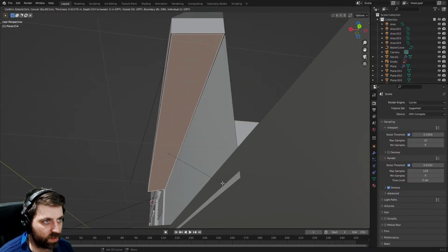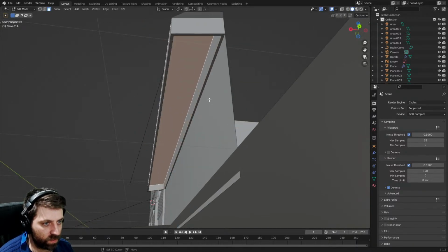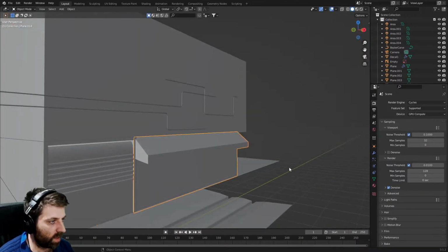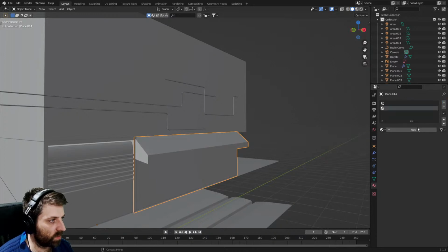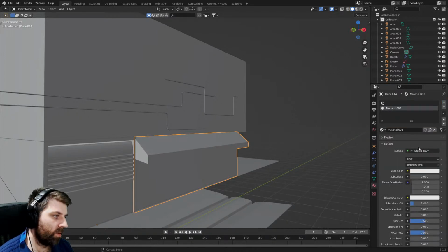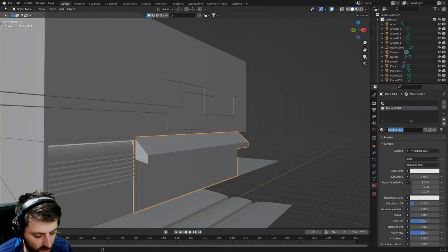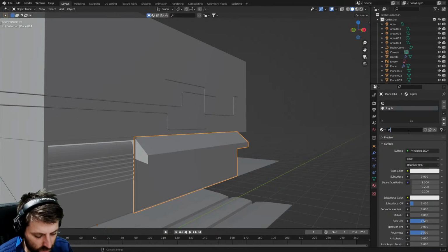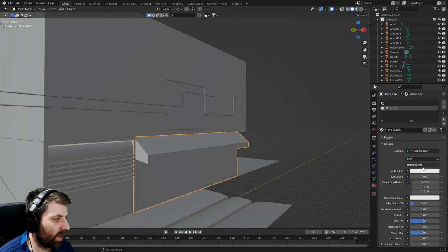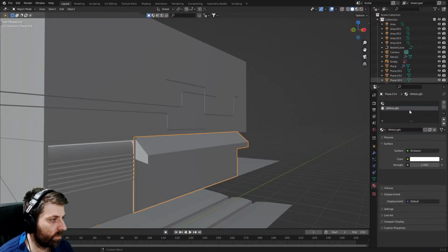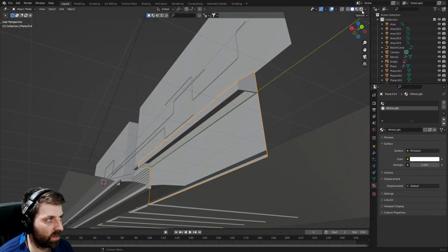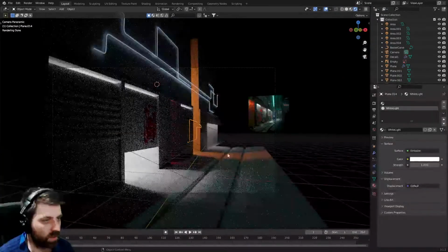And then what we can do, come here, I got an idea. Let's press I to do an inset, E to extrude, scale X. Let's create two new materials. And this one here is going to be our lights. Actually, we'll call it a white light. Let's change that to emission 1, and we're going to click assign. What's that going to look like?